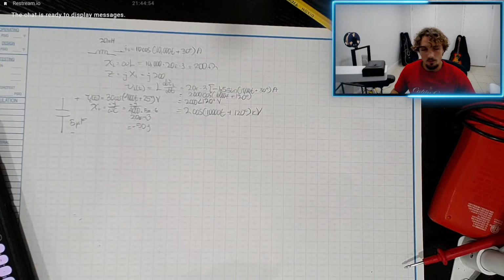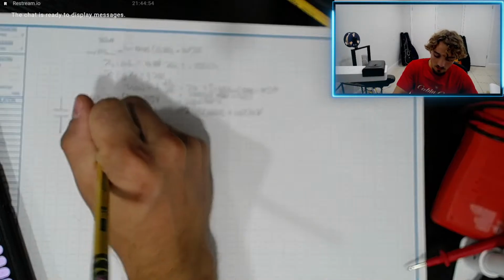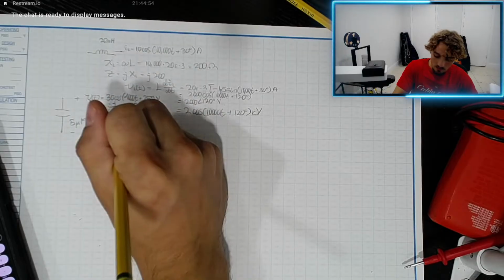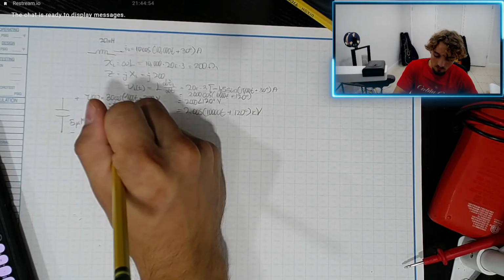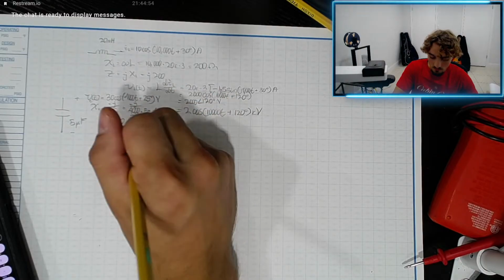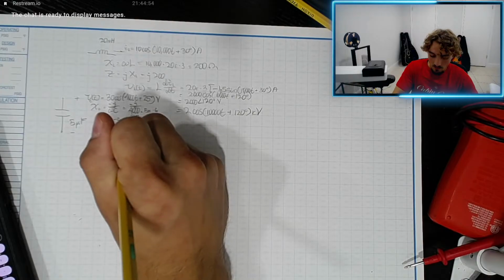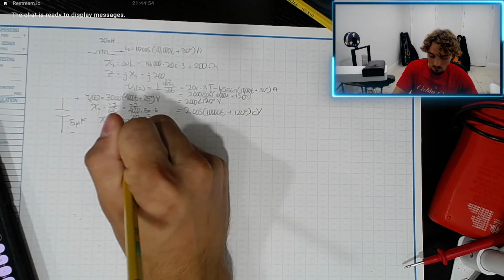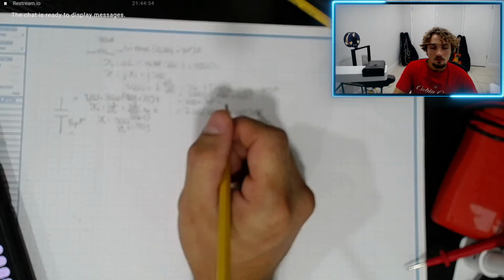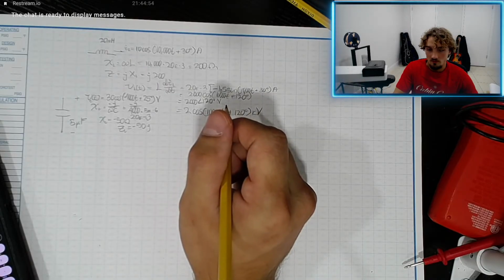So now, the impedance of the capacitor. Okay, actually, the reactance XC. XC equals just negative 50 ohm. And then this is the impedance, right? As you see, negative 50 j. The steady state impedance. The phase voltage.